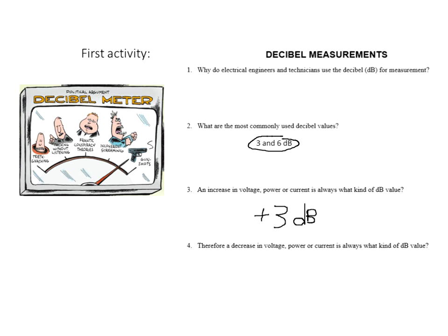increasing the voltage, power, or current, which will always be a positive value, as in number 3 here. So if you have a positive 3 dB, you know you're increasing the number of volts, power, or current. Likewise, if I have a negative number of decibels, for example, negative 6 dB, we're just focusing on the sign in front. If we have a negative 6 dB, that means we're going to have a smaller number of voltage, power, or current.